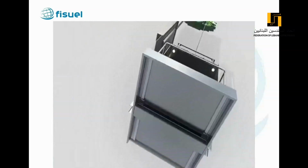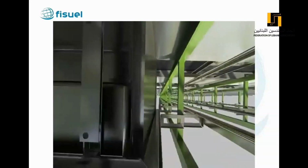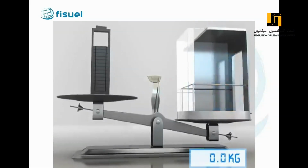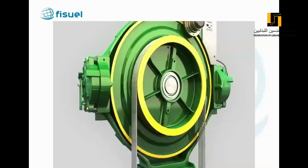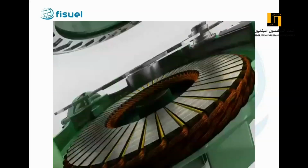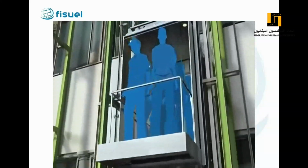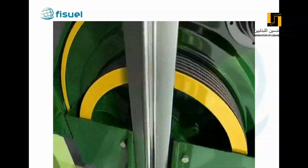The car and counterweight run up and down the elevator shaft, and the hoisting machine drives them in opposite directions. The car weight is usually different from that of the counterweight, depending on the number of passengers inside the car. When a fully loaded car starts to move, the motor uses electric power to accelerate the car to full speed. Once the elevator reaches the correct speed, the motor needs to continuously impose a corresponding electromagnetic braking force in order to overcome gravity and ensure the speed remains constant at the nominal speed of the elevator.